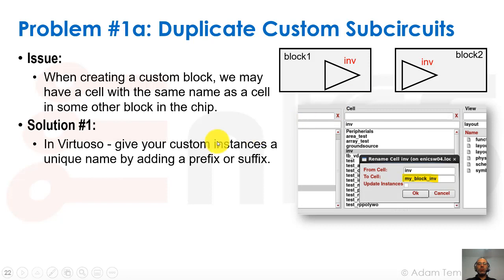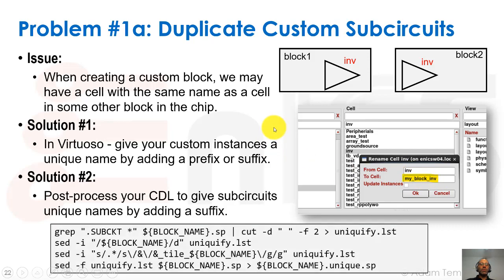So the first solution is this. In Virtuoso, we should give custom instances a unique name by adding a prefix or a suffix. So we should rename our cell inverter to myblock_inverter. And assuming myblock is going to be something that's kind of unique to this block in the design, we won't have this problem afterwards.